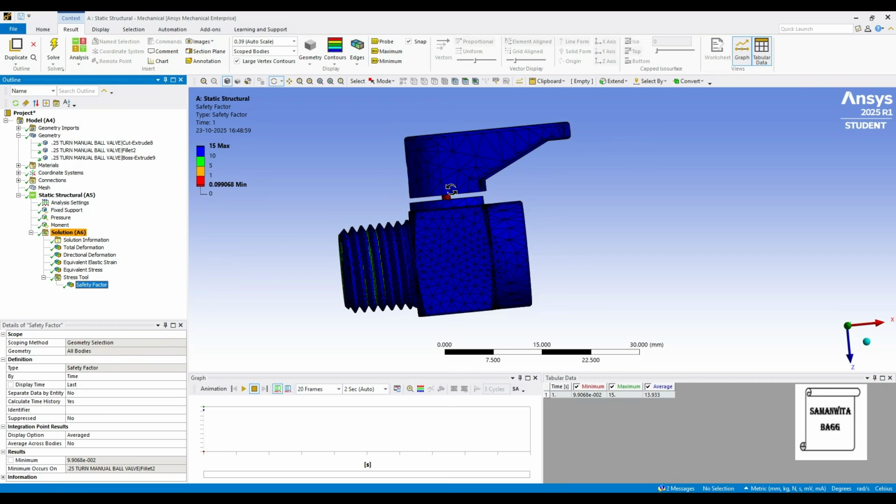Cost is again a very important factor which people generally argue upon, that plastic is going to be the cheapest, then comes your stainless steel, and finally comes brass. Brass again is going to be costlier. But the life, that is the longevity of brass, is going to be maximum. Then you have stainless steel, and finally the reduced one is your plastic. So plastic will not sustain under pressure and temperature accordingly. So you have to decide based on your application overall how you are going to use this valve. So choose the material for static structural analysis based on its pressure and moment value.